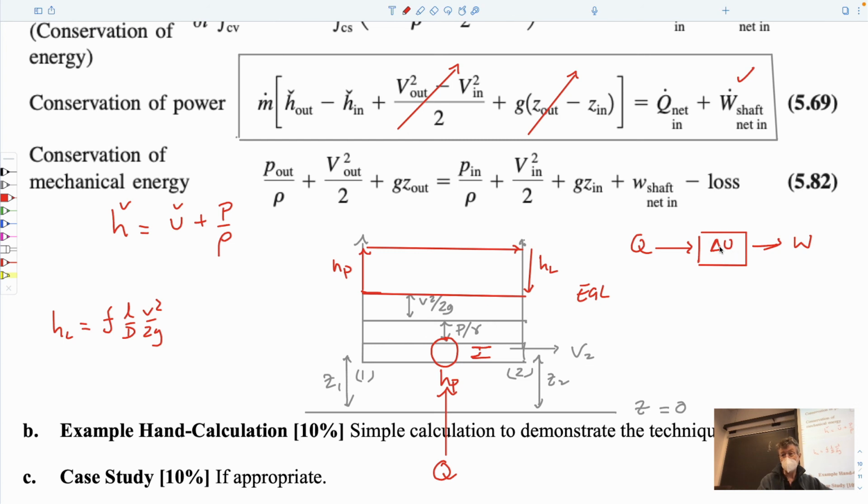And this internal energy can be defined most conveniently to include the influence of pressure, because a reservoir at depth not only has temperature associated with it, but it also has a certain amount of energy in compressed strain energy, which it can also deliver when you reduce the pressure from 40 bars at depth to 1 bar at the surface, because it'll expand in addition to the phase change effect by the temperature. So these are combined behaviors.